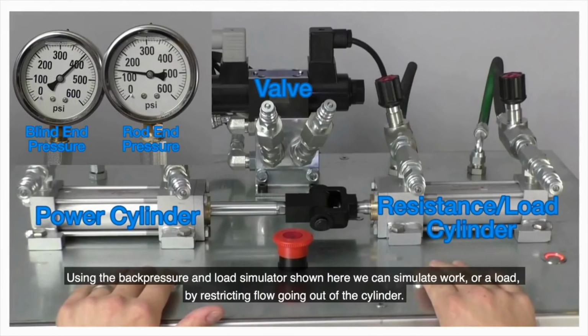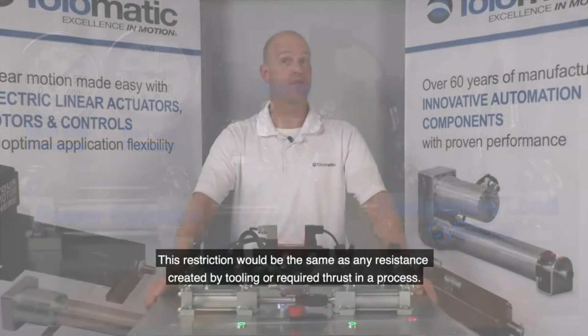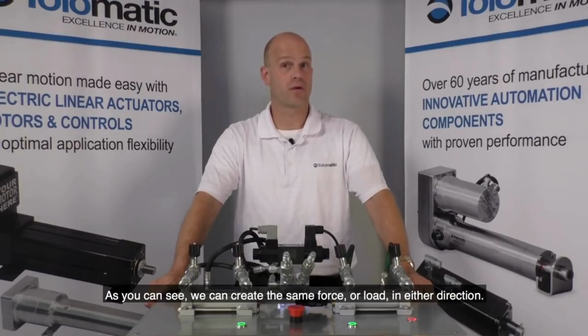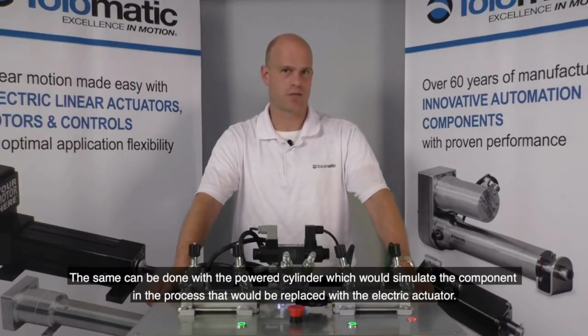Using the back pressure and load simulator shown here, we can simulate work or load by restricting the flow going out of the cylinder. This restriction would be the same as any resistance created by tooling or required thrust in a process. As you can see, we can create the same force or load in either direction. The same can be done with the powered cylinder, which would simulate the component in the process that would be replaced with the electric actuator.